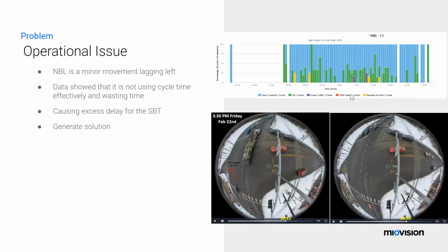One of the things that is important is to be able to evaluate this on all the competing movements at the intersection. From an operational perspective, a minor movement, let's say a left turn movement, if it's getting its green time, it should be serviced, and by the end of the queue, when the queue is served, it should terminate properly. That's very important for minor movements to behave this way. This is kind of an objective that needs to be reached.